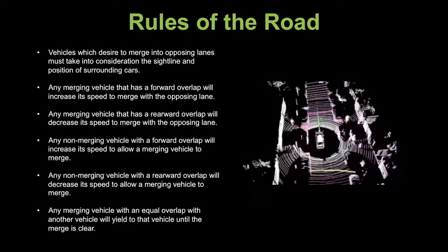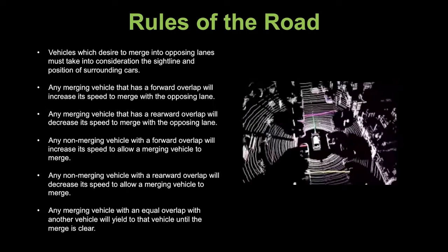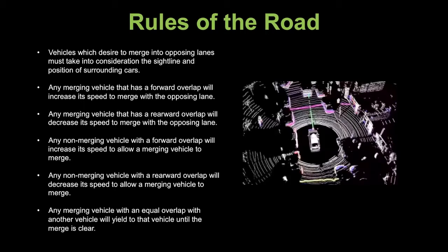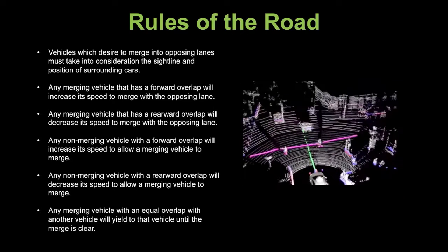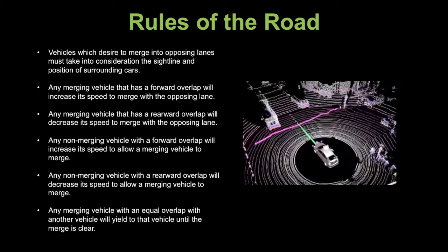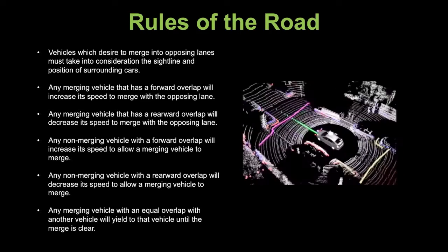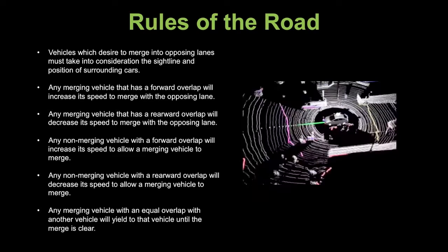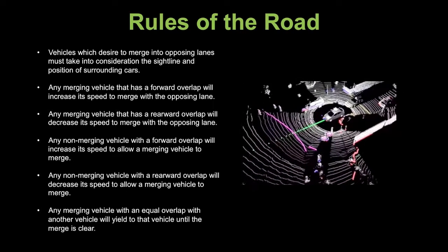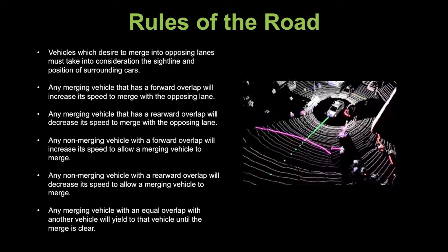There is also a particular case where any car that is stopped will cause all cars in that particular lane to merge into the opposing lane and avoid the stopped car. This procedure is also useful for cars which may be slower than cars behind them. When a faster car comes up to a slower car, and this causes the faster car to slow or stop, the slower car will receive a merge command and merge into the opposing lane to give way to the faster car.